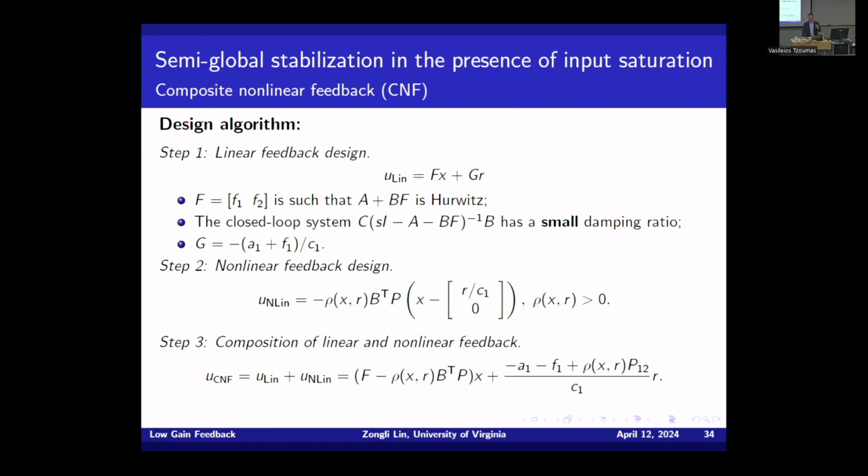So that means what? Your control effect will be, you start with a very small damping ratio and will shoot up very fast. But before you overshoot, you increase the gain. So it's like braking the system, right? And the damping ratio becomes large and you slow it down. And I'll show you this feedback.